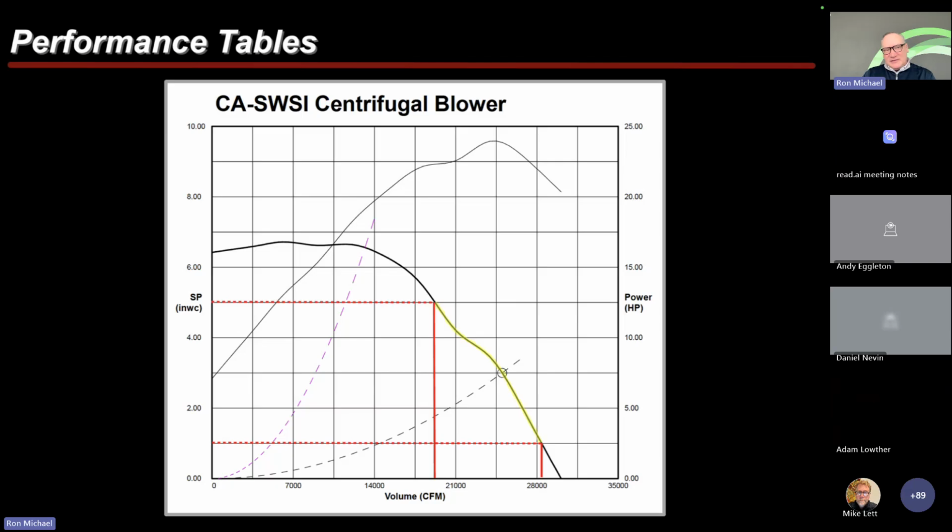And then just coming down to the very end of this, if you wanted to know what the characteristic is of the different type fans that we have available, you can use the exact same guide. Highlight a range, dash the lines over to pressure drop and flow, and you're going to understand the characteristic of that individual fan and what its capabilities are.